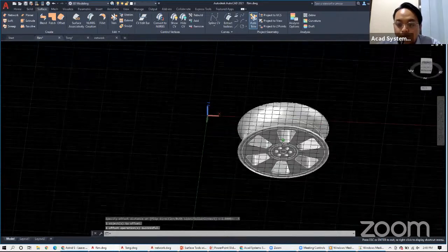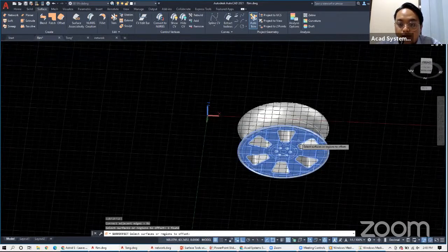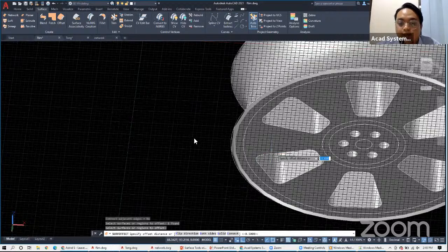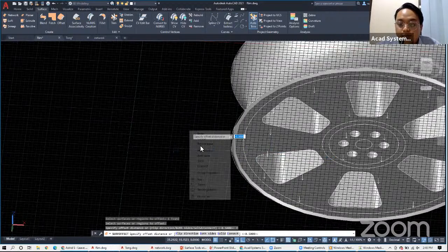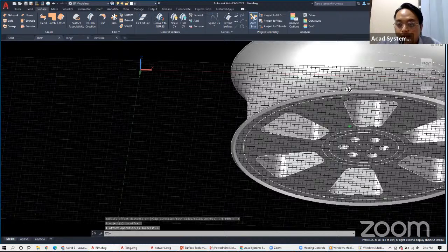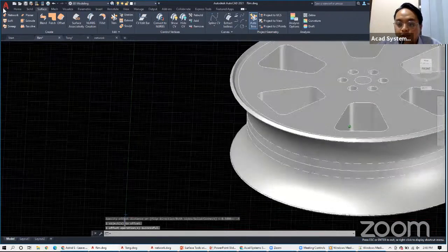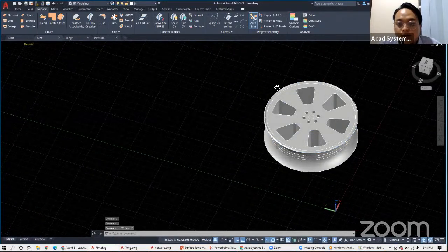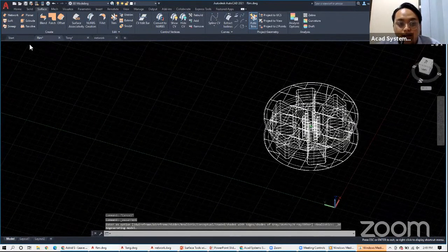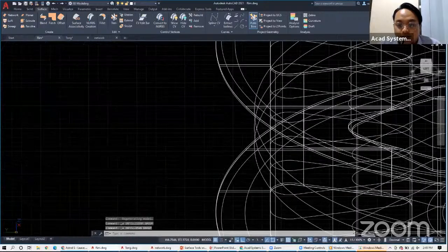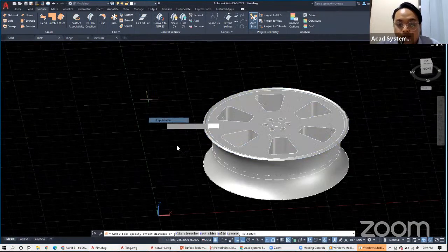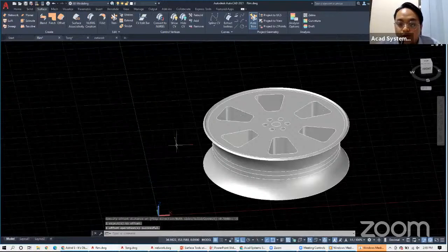And then I repeat the same. Okay. And then enter. You can see, let's say I have the direction. Okay. The direction is inwards and same 0.5. Okay. Now that our upper part and lower part is the solid, you can see here. Oops. Oh yeah, I forgot because I didn't select the solid. Okay, that was my fault. Just okay, our direction is flip inwards and then create solid. So 0.5. So now we have our solid here.